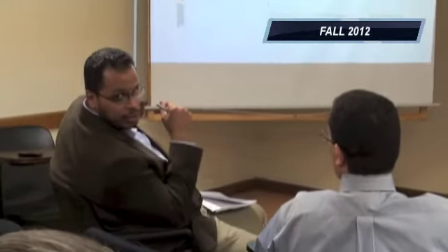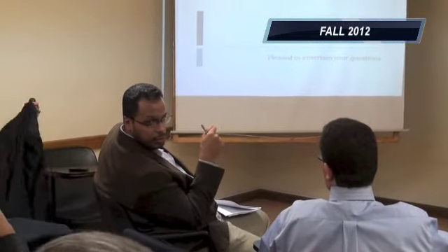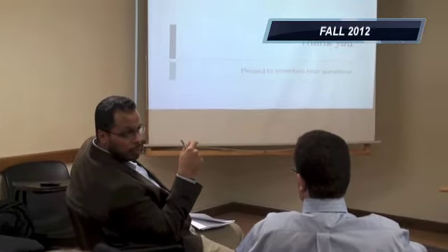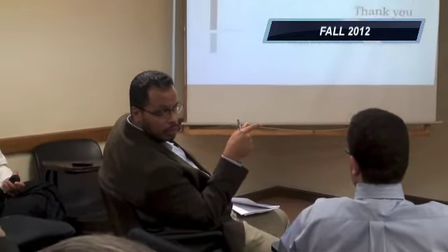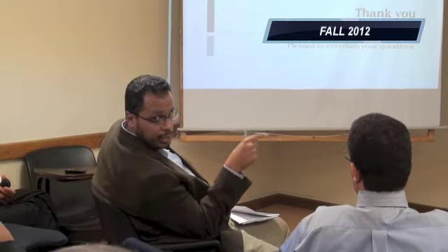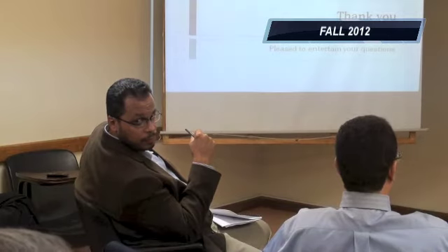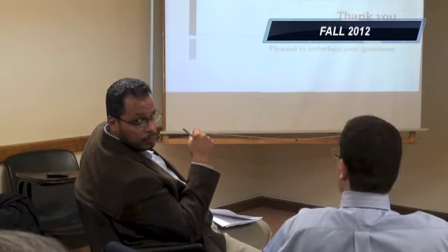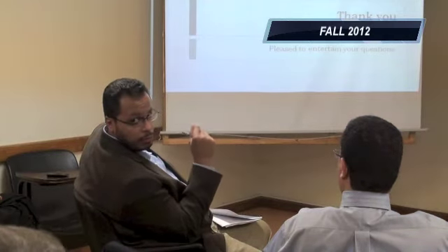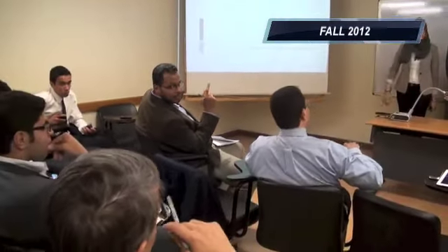I have a clarification on this. As the angle changes, the straining actions on the deck change. The moment and the axial forces change, because they are components of the cable forces, so there will be an optimization, probably through the section design, between the axial force and moment interaction on the deck. And basically that minimizes the cross-section. And do you estimate the volume of work in that part to be time consuming? No, it shouldn't take long. This is a cross-section design only, on the software. I got worried when I heard parametric study, I thought that would be a whole lot of work.